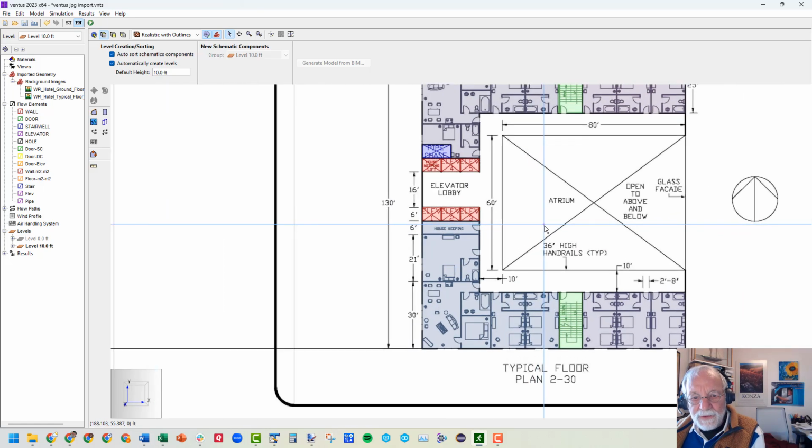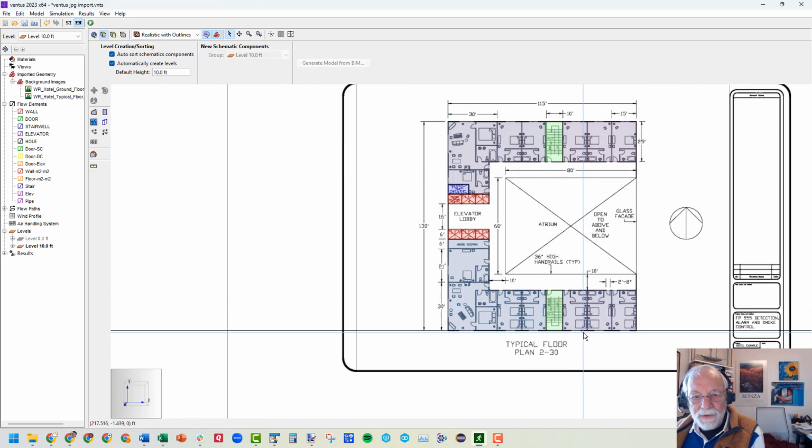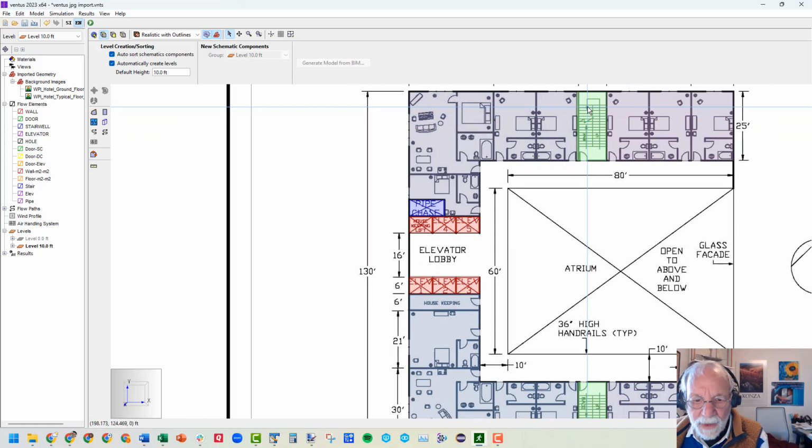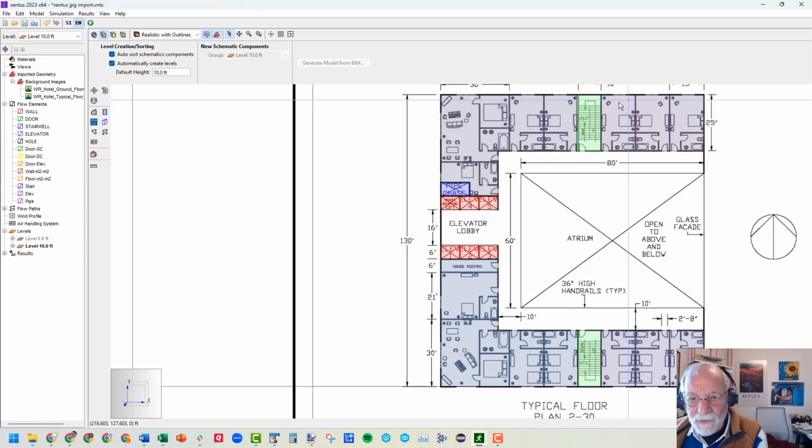And yes, you can see, this image now aligns with that. And you can see the rooms are now different. So I have different doorways here. So that's why I didn't want to copy the flow paths from the first floor to the second floor. What I'm going to do is the work of making all of my flow paths for the wall leakage and the doors. And then I'm going to show you how we create the leakage from the floor to the room below.